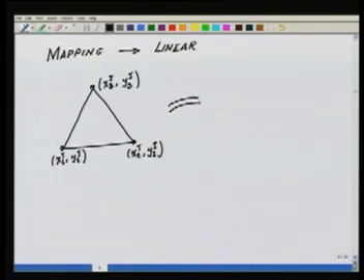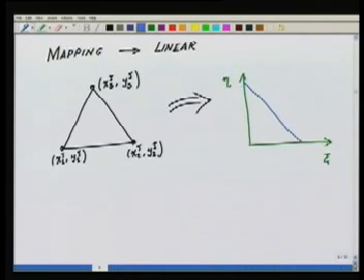This we are going to map to a master element given in terms of the coordinate system psi eta and defined as this. Our master element is going to be such that the first node has coordinates 0, 0. So the nodes of the master element, I am numbering them with hat. The second node has coordinate 1, 0. Third node has coordinate 0, 1.